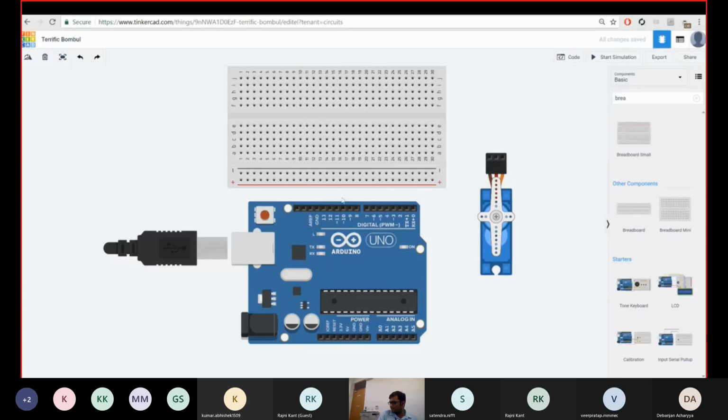So simply connecting these to the Arduino would be fine, but since I want to give you all more experience with the breadboard, we're going to be using the breadboard and then connecting them to the servo itself. So starting with the ground, I'm going to plug that into the negative port here.